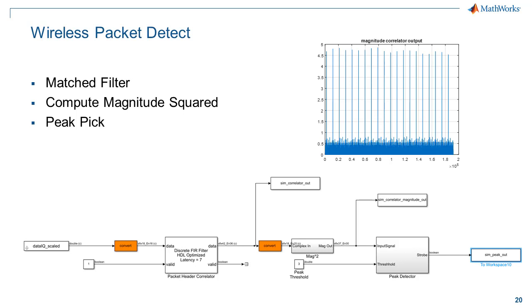We then quantized that output back to 18 bits. And we had a mathematical prediction for how much error we should get there, and we measured something that was exactly on that order using MATLAB and Simulink. And then we did the magnitude squared full precision, but we know there'll be a little bit of a buildup from the quantization error that we had here, and that was all measured consistently.